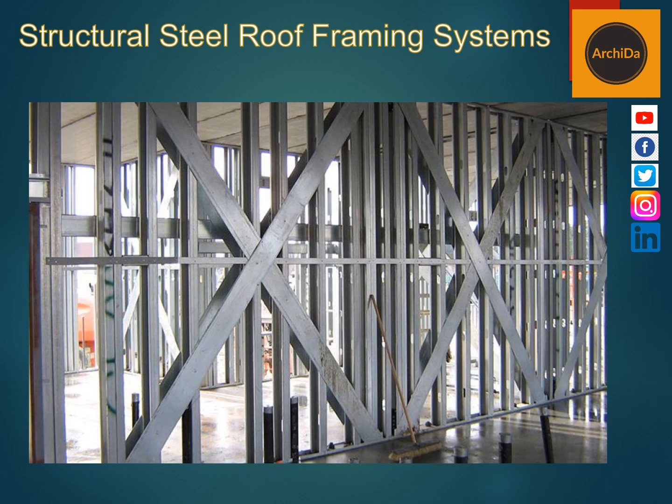There are several cases in which a wall-bearing frame system is suitable to be used. For example, a single-story house in which steel beams are used to carry wall and floor loads, and the ends of the steel beams are placed on foundation walls. A further application of the wall-bearing system is the utilization of steel beams known as lintels over wall openings like doors and windows.